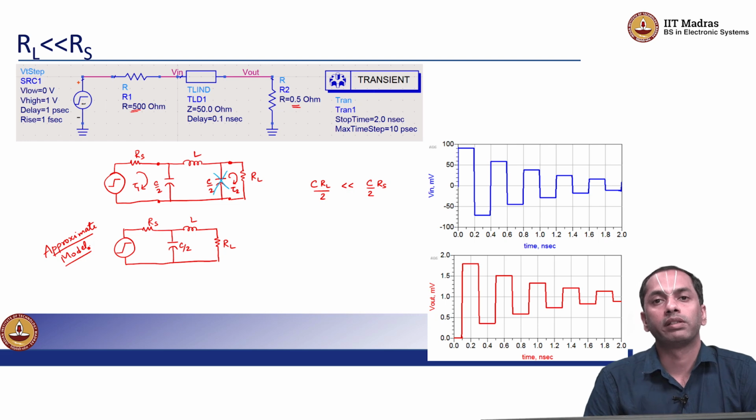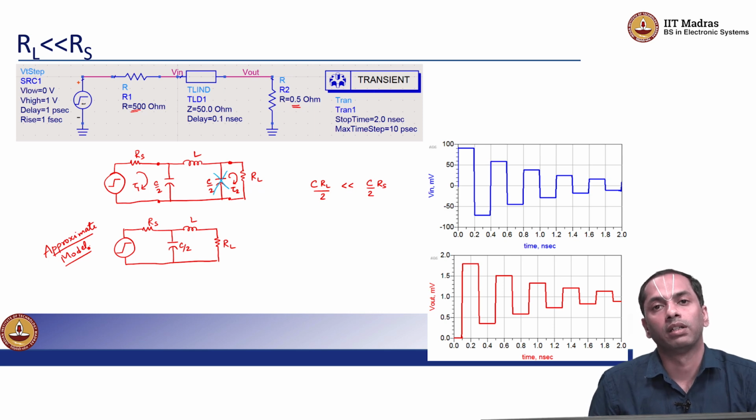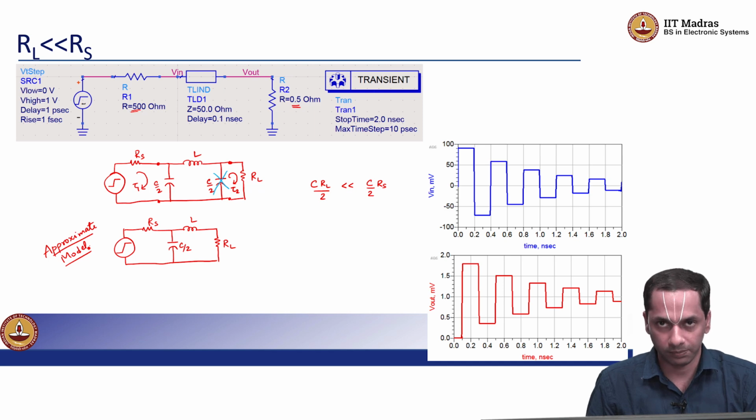So hopefully these three situations that I have portrayed, and this idea of estimating the time constants using a simple lossless model for the transmission line with a lumped inductor and capacitor, is a useful exercise that you can run in your heads in actual situations, and perhaps explain or even make comments regarding the source and load impedances, or the nature of the transmission line, and so on. So when you see transient behaviors that are akin to RC charging, RL charging or RLC ringing, you immediately think of this kind of scenario, so that you can simplify the situation and better get to grips with where you need to make the adjustments.